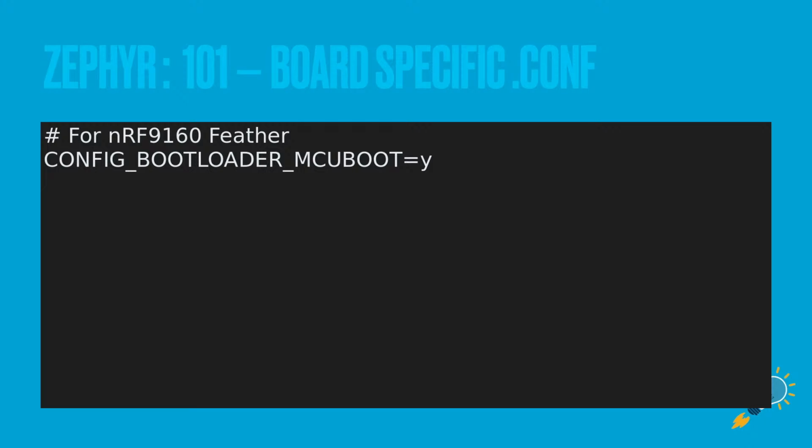And then I mentioned that boards folder. This is circuit_dojo_feather, or nrf9160_feather_ns.conf. I like using that board because it has a bootloader built into it that you can do transfers over USB via the UART to USB adapter, or the I2C.